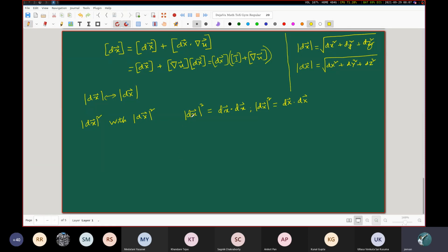Now, all this is fine. I mean, these kinds of algebraic manipulations, clever tricks, all that is fine. But we must take a step back and ask ourselves, what for are we doing all these things? Because let us not lose sight of the fact that we want to arrive at a point where we will be able to write down some expressions for the strain transformations, meaning that we are working with the strains in a particular coordinate system. If we change or rotate our coordinate system, what will be the values of the strains there? So how does all of this help? And for that, I will definitely show you the steps and all the details.